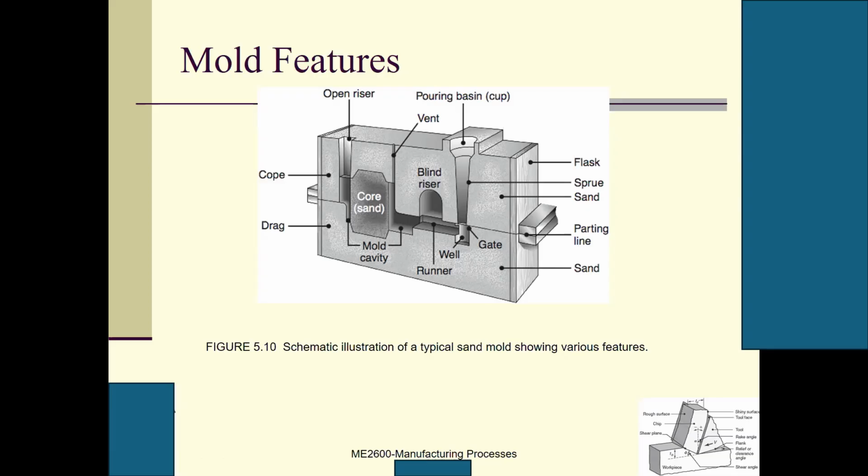Is it because when you pour molten metal in the sand mold, the sand will maintain its structure, and your mold will keep its shape? Who is speaking? This is Reed. Yeah, that's awesome. Because the sand, silicon oxide, has a very high melting temperature, it will not be affected by the molten metal. That's a very great point.